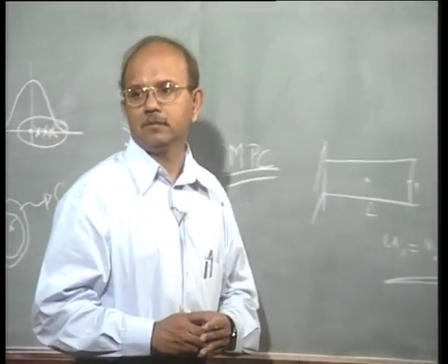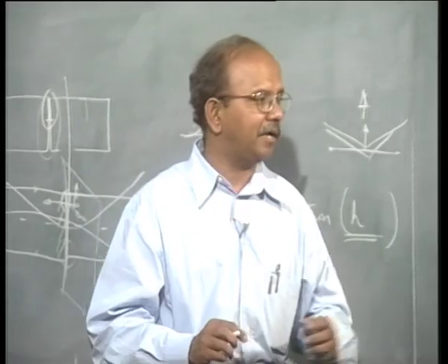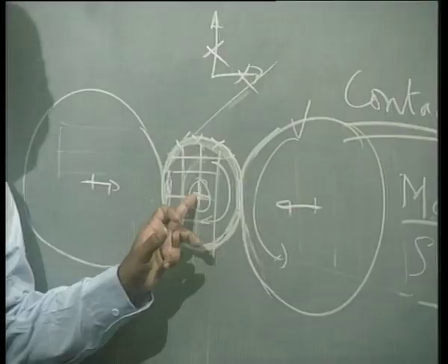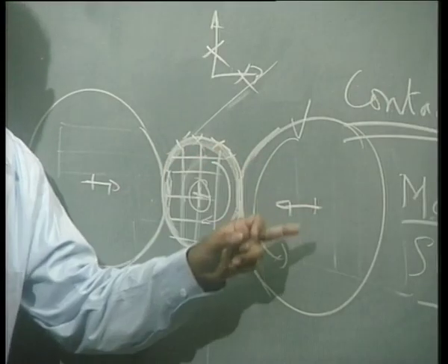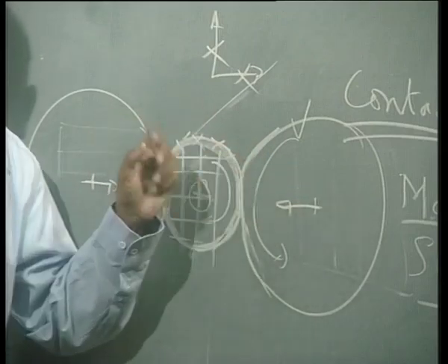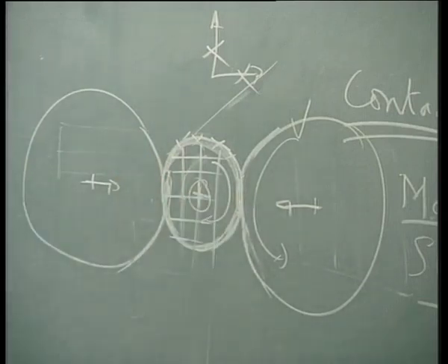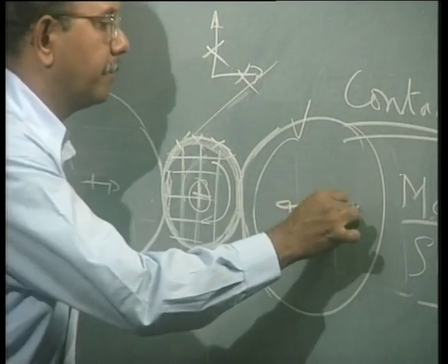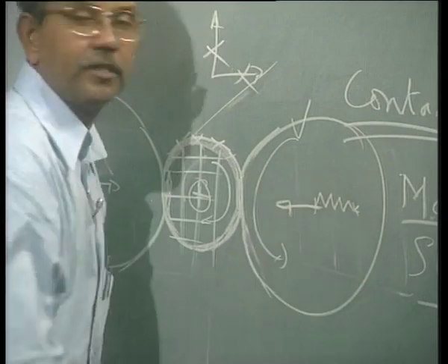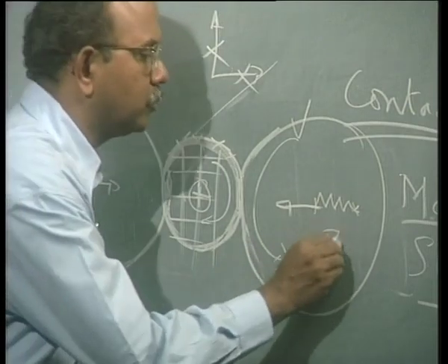So what we do now is that we have to place this complete system on a much stronger footing, or robust footing, I would say, numerically robust footing than what it is now. So we put one more node here, we put a spring element there, and give some arbitrary k value, say about 5000 or whatever it is.